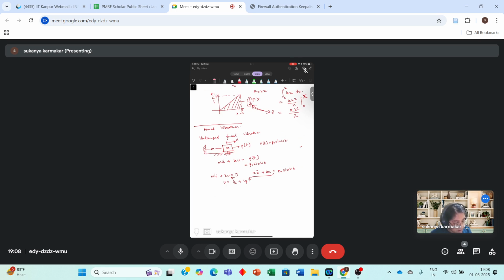For u particular, you assume a particular solution, like what we did in the free vibration case, where you assume e to the power st. Here also you are assuming some form, that u particular is, let's say, c sine of omega t. Take the derivative, substitute it, get the solution.